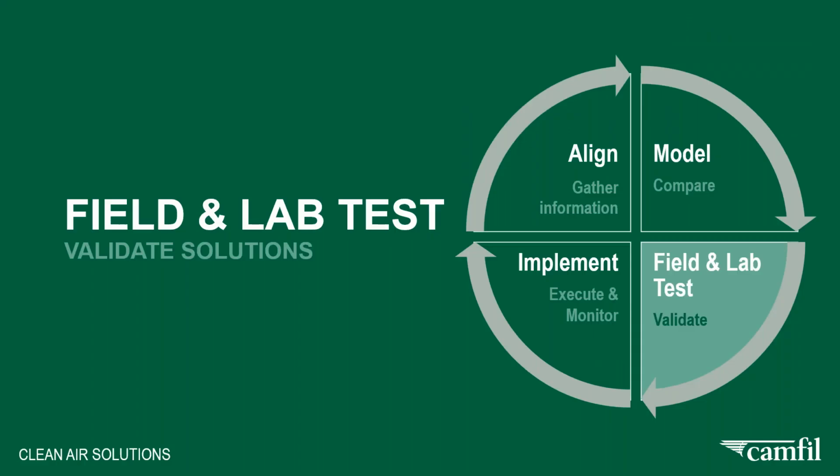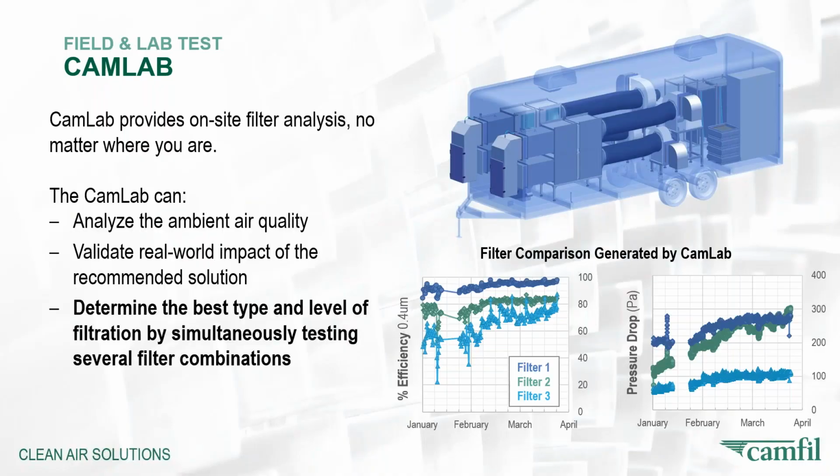The third step is to validate your solution. And how are we going to do that? We're going to do that by going to the field and lab to test those recommended solutions. The Cam Lab is a standalone trailer with 4 independent duct systems. It allows multiple solutions to be monitored side by side. It also takes ambient temperature, humidity, particle counts, DP readings, anywhere from 20 second intervals to 5 minutes.